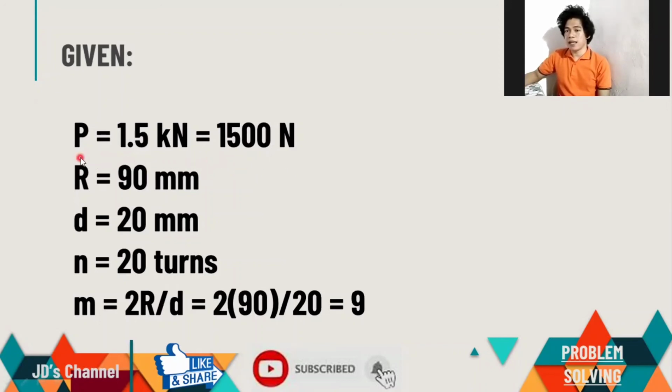But if it is less than 1,000, we use a light spring only. Since this is more than 1,000, that is a clue that this is under the heavy spring. So that's why we get the value of M. Since we are only given the radius, M is 2R over the diameter of our wire. That is 2 times 90 over 20, so we get the value, which is 9.